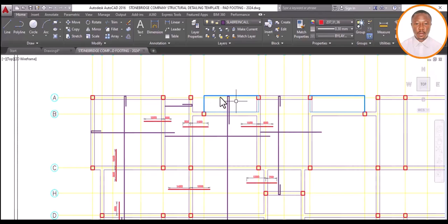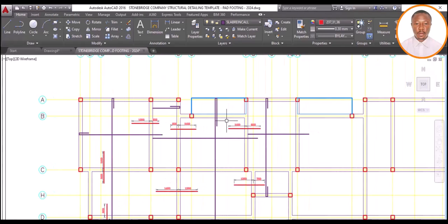For example, if from this point into this place, maybe from here to here is 1.5, and you also put 1.5 equal, the force here can cut off this place, causing the reinforcement to come out, or cause a shear here. And that is why that principle needs to be applied here. So invariably we are going to edit this particular reinforcement at this point before we start calling out our rebars. Is that okay? Let's quickly do that.